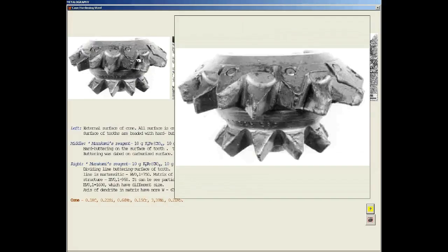On this picture you see a cut cone. The cutting elements here are created by teeth. Its surface is furnished with hard weld deposit based on tungsten carbide. On the circle you see holes which are filled with inserts of sintered carbide, which help to maintain the dimension given in this area while drilling.